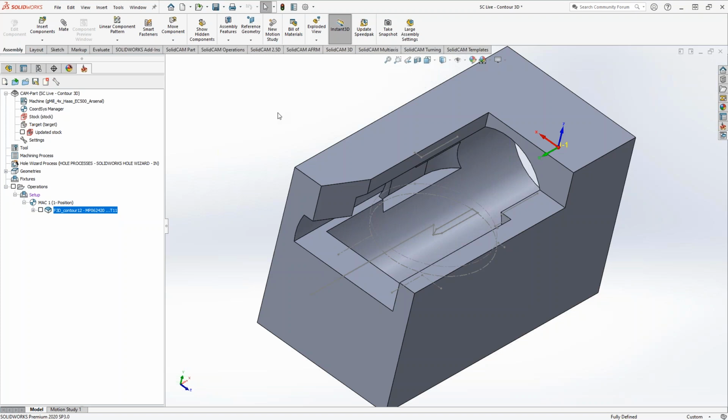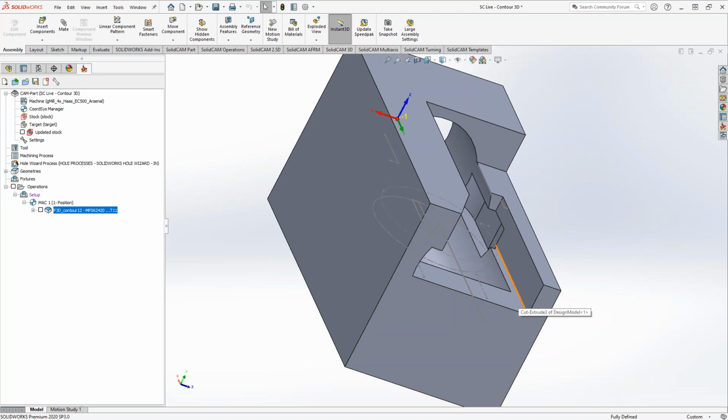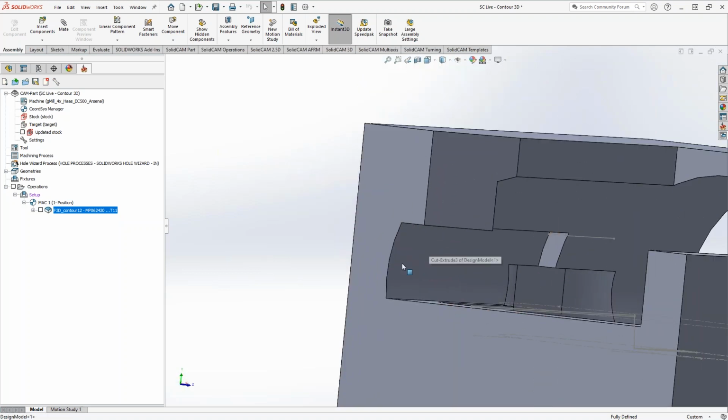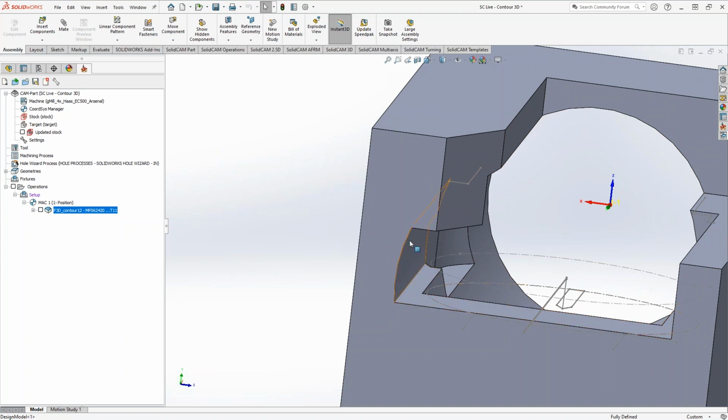I actually worked on this a lot, trying to keep it on the right side or the left side of the tool so that you can use cutter comp. But I just couldn't figure out how to stay on one side of the chain. So when I set it up as the center, it made it very easy because all it is is just offsets. If anything, this line right here is actually an offset from this side because, as you can see, there's a little bit of a curvature here. And when I tried to go down the center here, it actually gouged there.